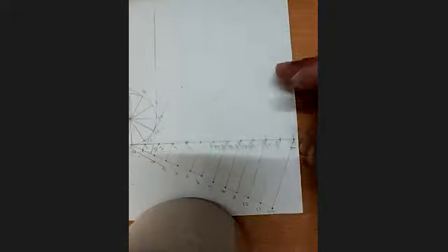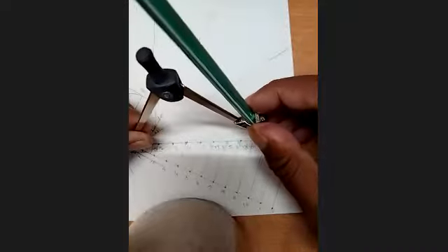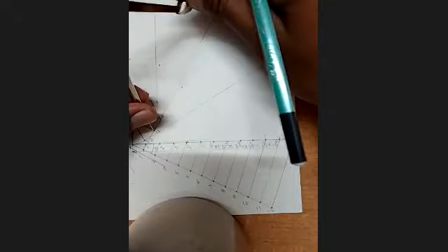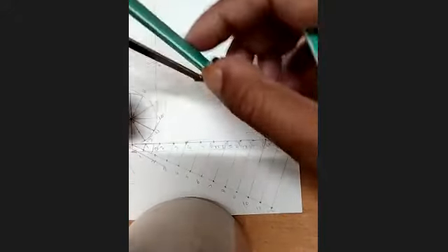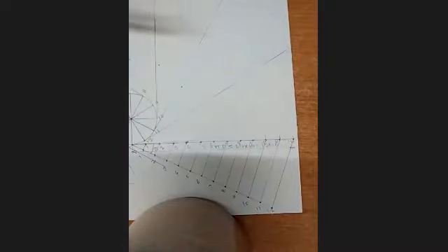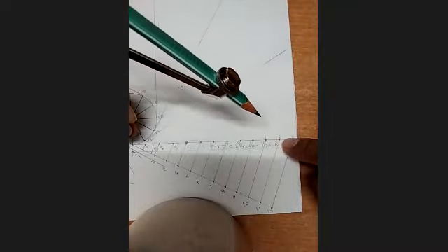But in an involute, you can go on marking the point by reducing one by one, then take to 10, keep here, and cut it. Next, you cut it by reducing one by one. But in that case, joining the curve using a French curve is quite difficult. So I will give you an alternative. This is the actual procedure. When you try it with AutoCAD, this division you must do, but there are advanced tools, so you can get the division very quickly.